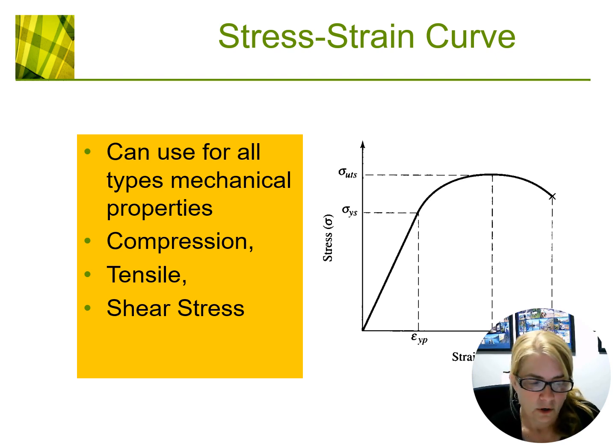But in between there, we've got the stress on the side, the strain on the bottom. The first marker we come to is the proportional limit. Once it starts to go up, the proportional limit, the stress and strain are no longer the same, it's not as stiff, a rubber band's not going to bounce back quite as well. There's more strain versus stress. Then we have the yield strength, where it deforms pretty fast on the way to the ultimate strength at the end, where it actually breaks. And I can show you that in graph form with it labeled, so remind me during class and I'll let you take a picture of that.